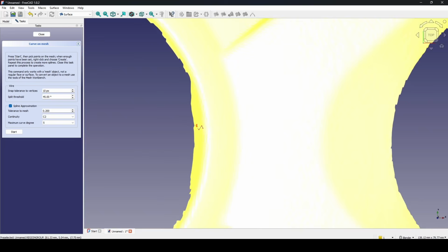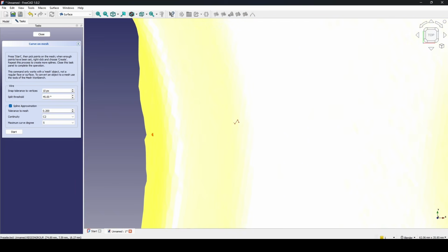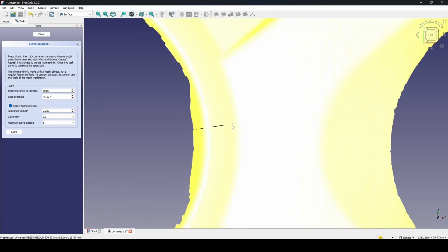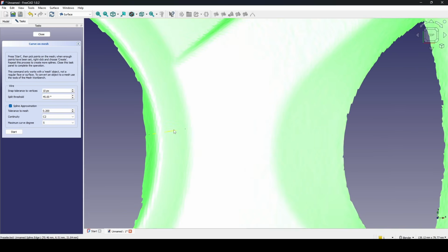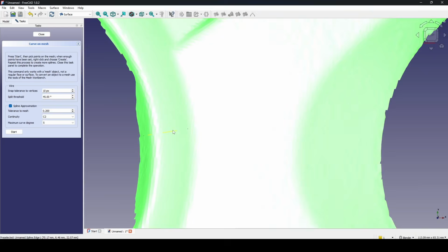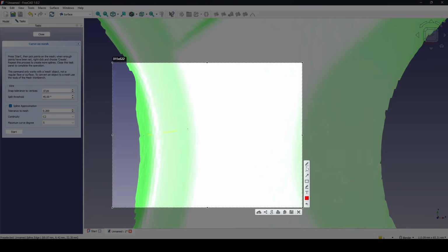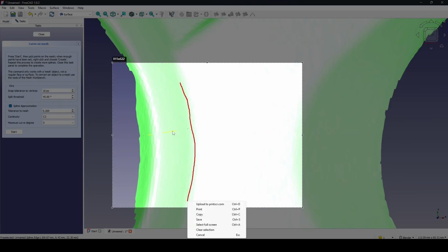So I click on here, and then I click somewhere in here, as you can see, and I right click on it, go to create, and we have one small line here. Okay, and you can see this curve over here is the fillet, and I want my line to be somewhere in here. I don't want it to touch the center line. Okay, closer to the fillet line.